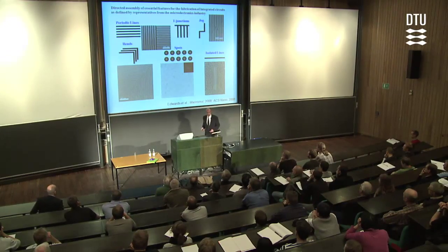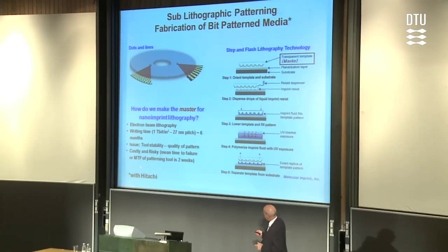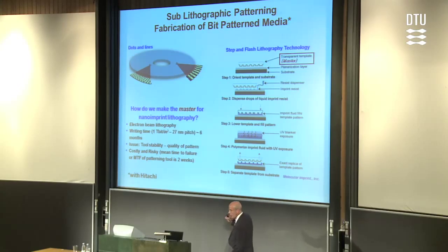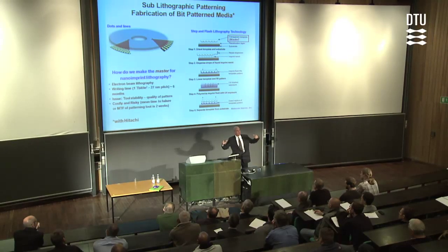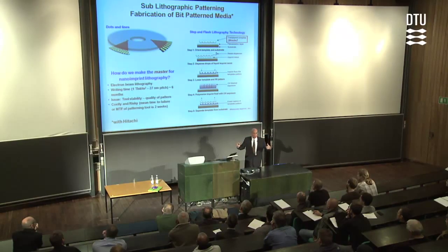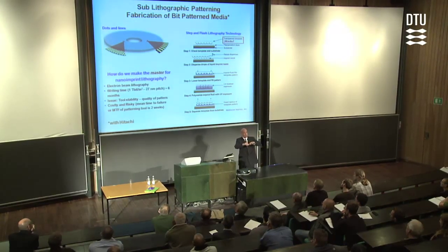And we think that one of the first applications that might be coming next year would be in the area of memory devices. So hard disks for very high density storage, terabyte disks. The way it's going to work is as follows. This is work that we're doing with Hitachi. Currently, your hard drives consist of a uniform magnetic film which you pattern, right? And you create magnetization in local domains. The problem is that because the magnetic film is uniform, those domains, for them to be stable, have to be pretty large. In order to have a higher density, one thing that you could do is create tiny little spots, as you see over here, all of them isolated with polymer in between.